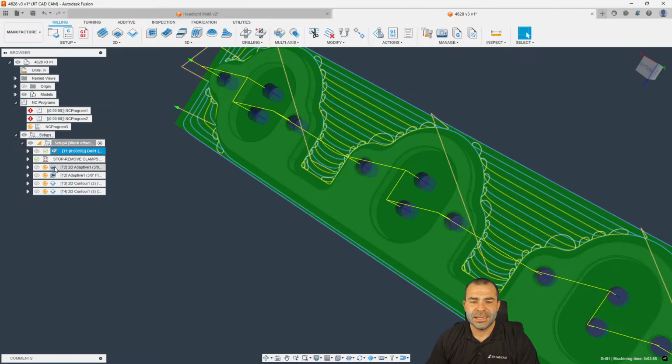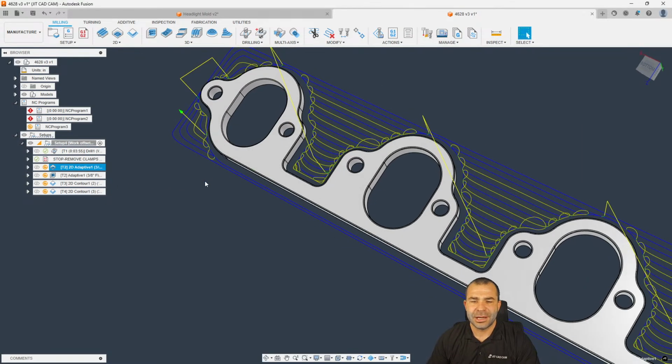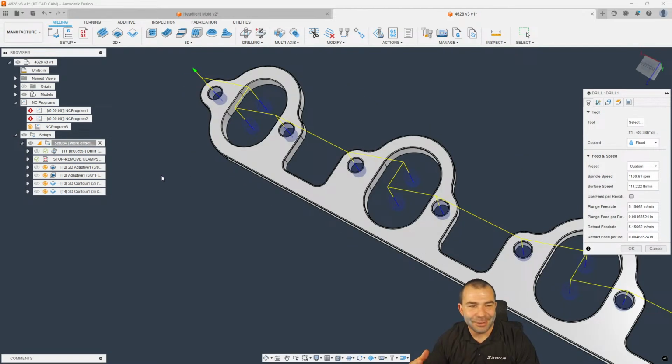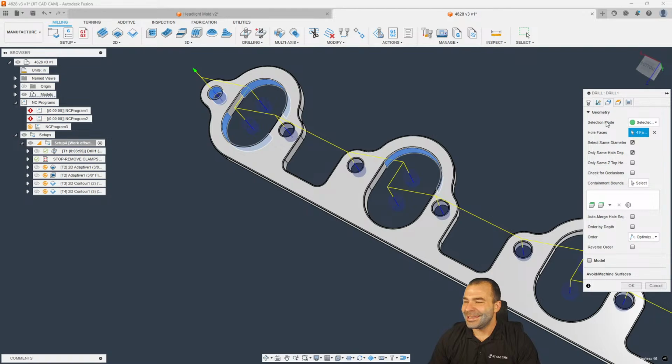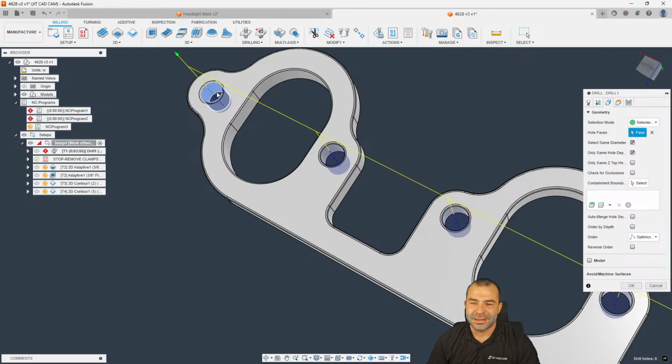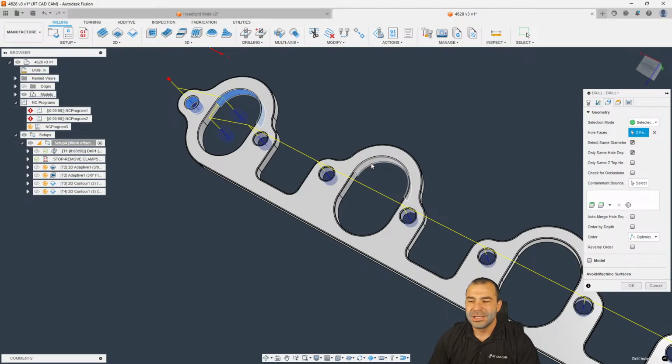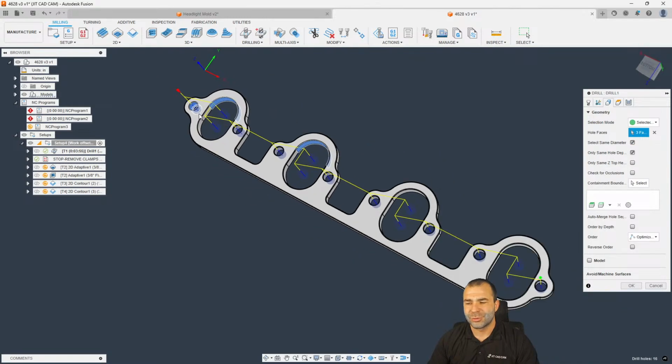And as you can see, you have that ability to do things automatically. Now, I did see a mistake here on Wes's part. I see him in chat, Wes. Shout out to you, man. Oh, nope, he did select same size diameter. Awesome. So when you go through and select stuff like this, you can pick one arc and then it automatically finds all the other arcs or cylinders. So as you can see, within 3 mouse clicks and having select same size diameter turned on, I've been able to go through and pre-drill everything.